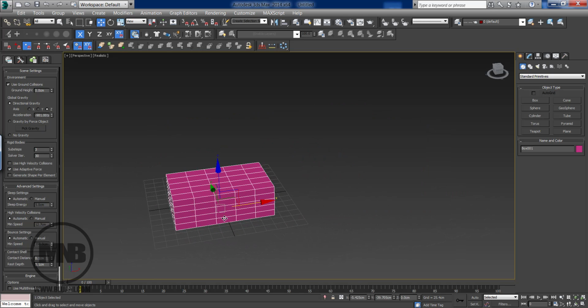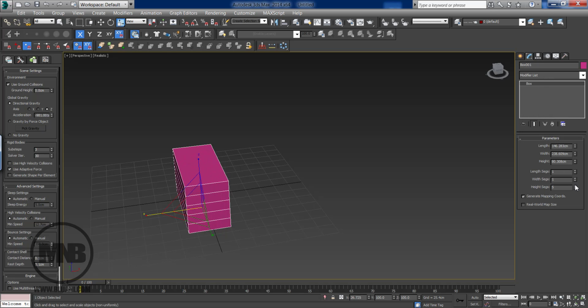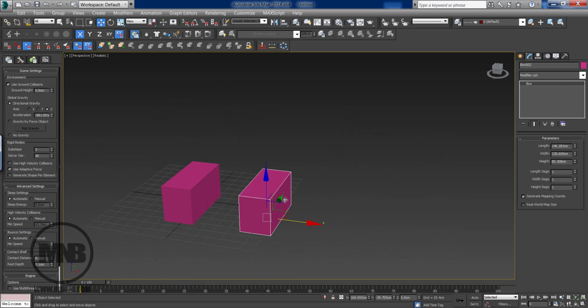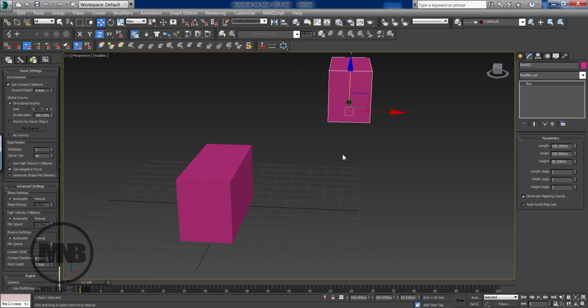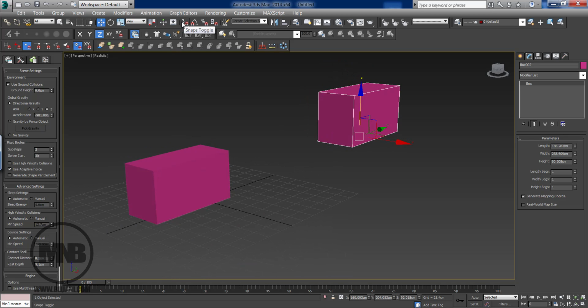Now I want to create some snappings. If I have this object, I'm going to reduce my segments from the previous. I'm going to copy another object maybe, and also move it on X, Y, Z. In here, first of all, I'm going to access my snap tools. Snap tools are in here, which is the snap toggles icon, or the shortcut is S. If you press S, you can turn it on. And in Max, as you have already maybe realized, the same shortcut that turns any option on, let's say this is snapping on, the same shortcut will turn it off.